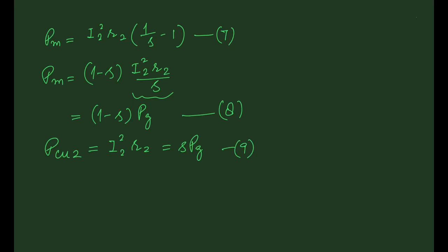This analysis was carried out on a per phase basis, and hence for a three-phase machine, the air gap power Pg will be 3 times the air gap power per phase.